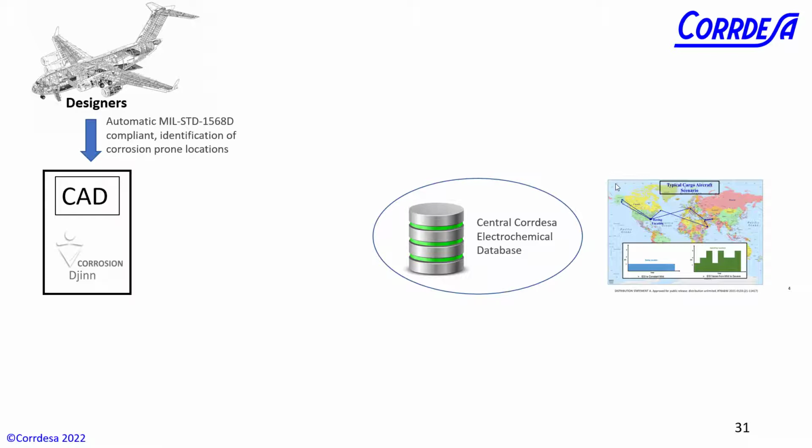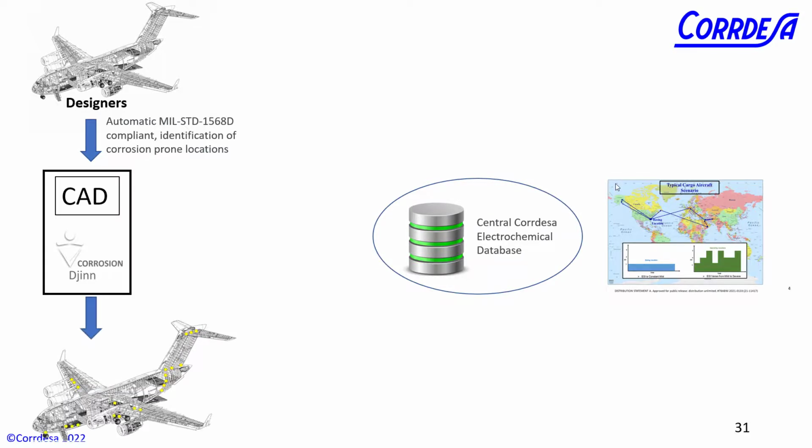Just as I did 2 or 3 material couples in my demo, that is now done for each and every interface, fastener, washer, nut, bolt within this whole system, done automatically. It's on a computer, so it's no problem. It's done fast, and that will give you your potential areas of high corrosion rate.